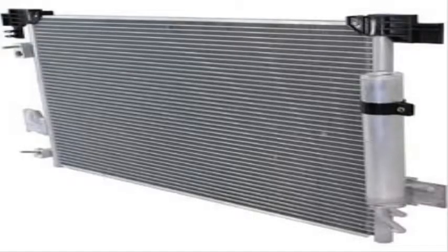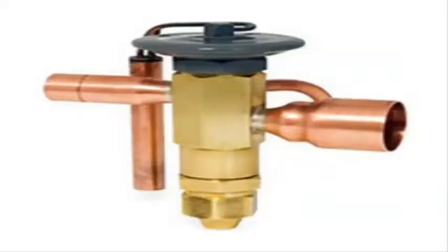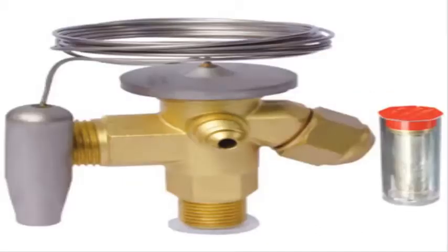For example, if cold refrigerant, 40 degrees Fahrenheit, flows through the evaporator and the air surrounding the evaporator is 75 degrees Fahrenheit, the cold 40 degrees Fahrenheit will absorb the heat from the 75 degrees Fahrenheit space. By absorbing the heat from the warm space, it also cools the space. It then transfers that heat to the condenser, high side, through the compressor.